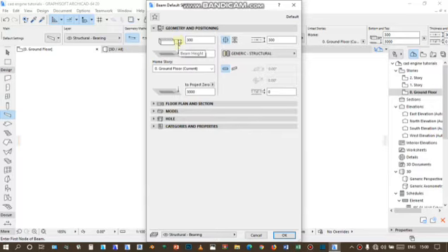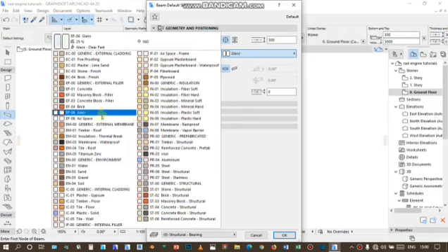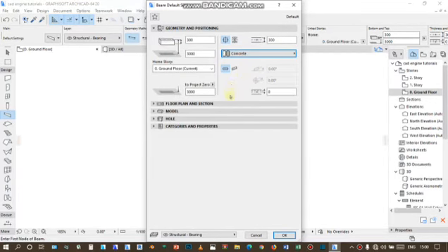As you can see, the arrow is pointing to the top of the beam. Here is the beam structure, and here is the one that you have a special design for. We will come to this when all of them are just outlined in one element. This is where you set the beam width, and here you set the material. It is always structural concrete or maybe any other thing, and here you set if it is inclined or not. Here you set the angle, you put in inclined beam. As you can see, this one has an inclination, so you set the angle here.